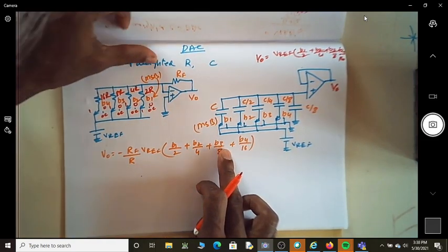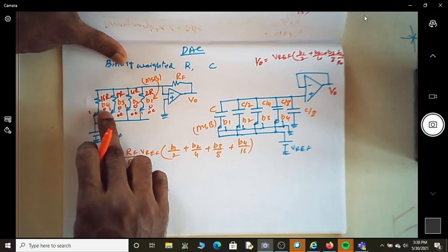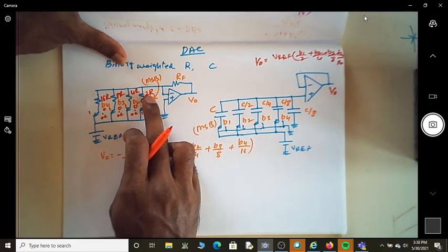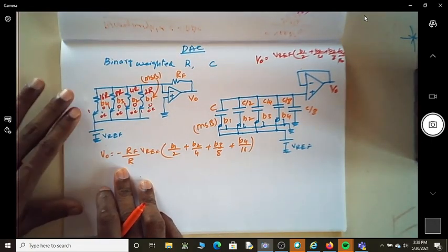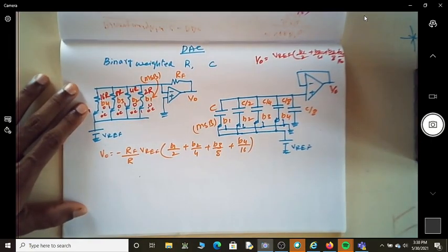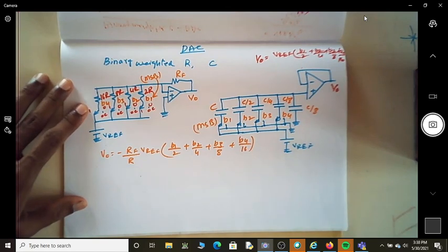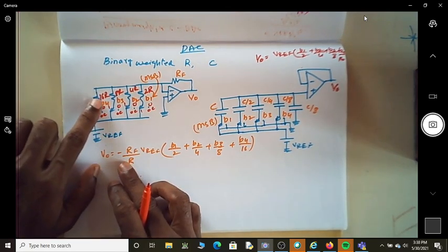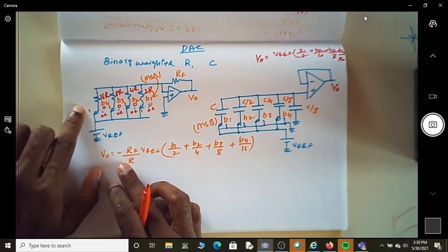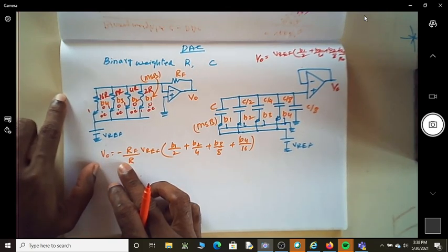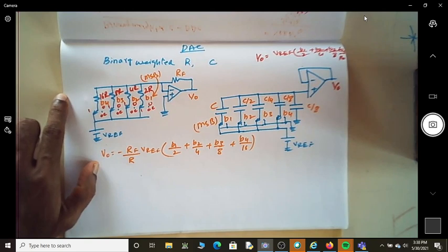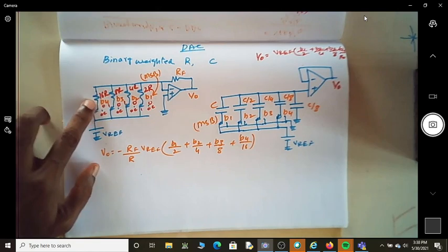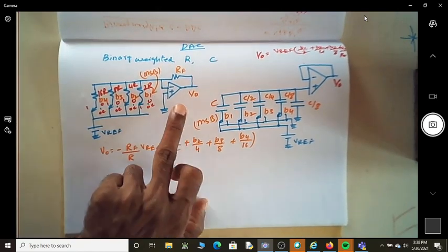input digital signal. So here, as we discussed in the detailed class, it is very difficult to realize resistors of different value on a VLSI. It is not so easy, and of course if the number of bits keeps on increasing, we know that after 16 it will become 32, then 64, then 128. So if the value of the resistance is not exactly those 2 power n, then we may end up with errors which will lead to INL and DNL.